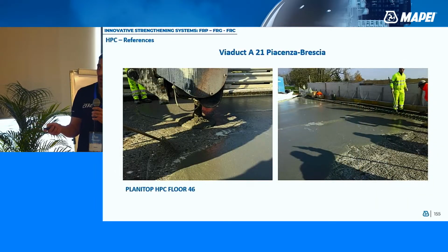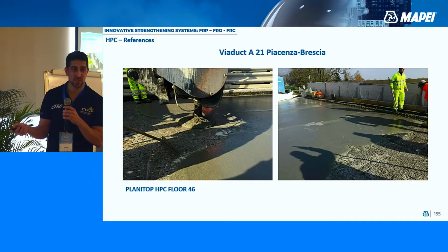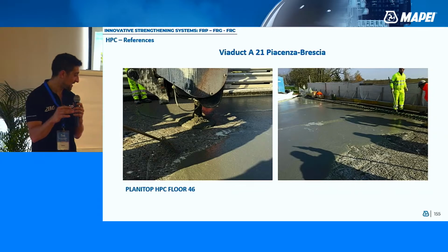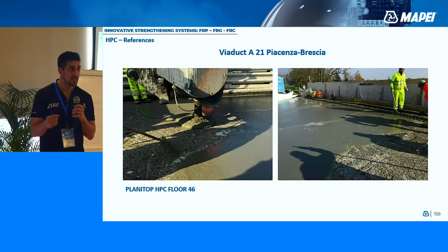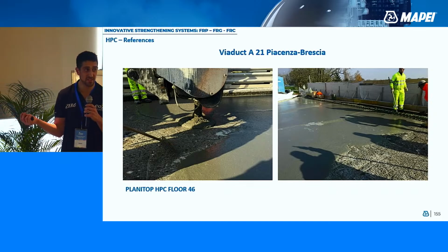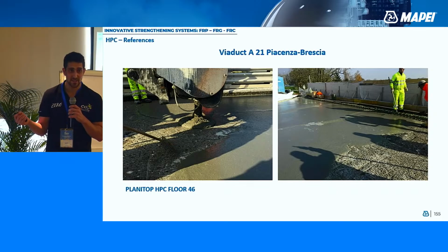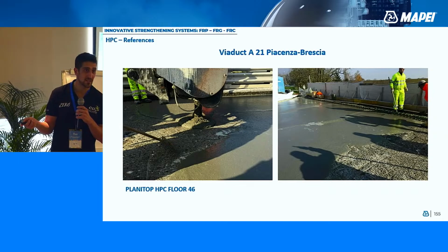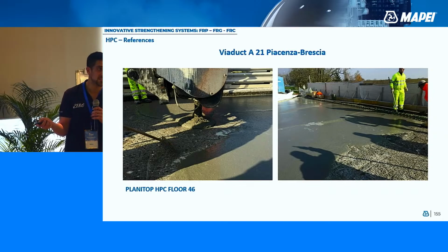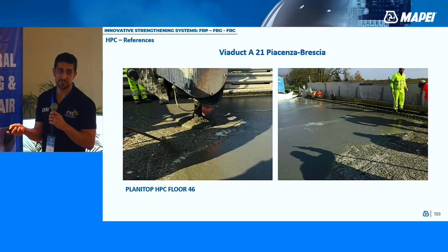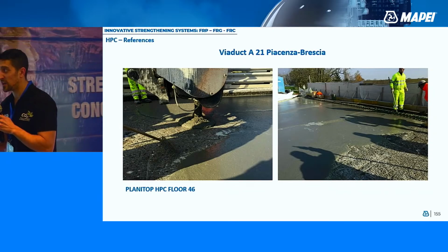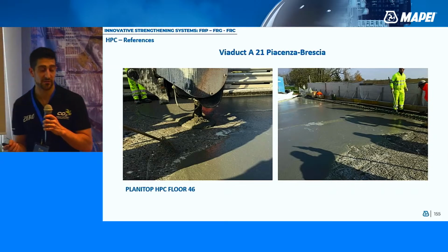Again, the application of the Planetop HPC on bridges. It's not only a product that can be applied for realizing concrete topping in civil building, but also for strengthening bridge decks. So even in this case, no steel, no shear connector, no electro-welded steel mesh, no steel, just a mortar with steel fiber, able to collaborate without any kind of connectors.